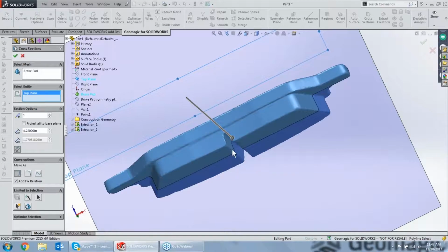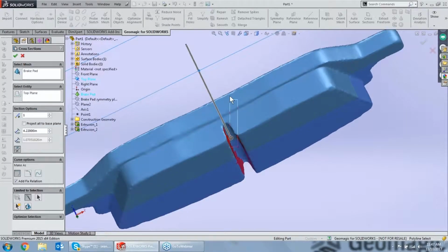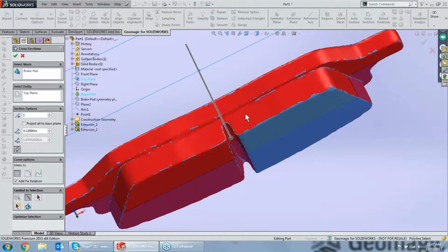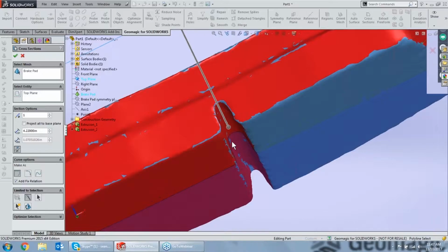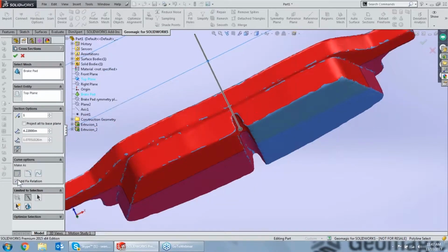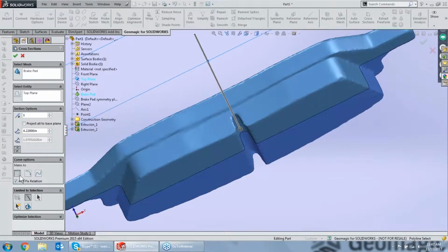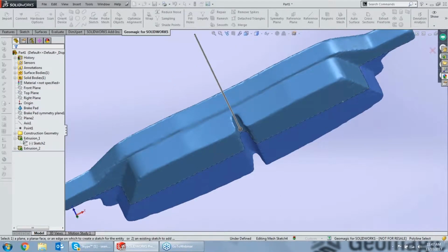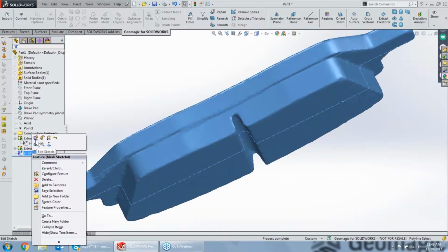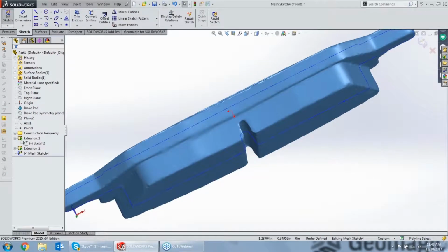And in this case, I'm only interested in this small feature in here. So I can actually say, just ignore everything else, but give me a cross section of this smaller area here, and it will build. You can see the black lines are starting to appear. Oops, went a little bit overboard there, but it'll build me a cross section only on the area that I'm trying to focus on. And in this case, we'll kind of ignore this whole thing and build this just as reference geometry, so that I can take this sketch here and just copy the areas that I'm interested in.